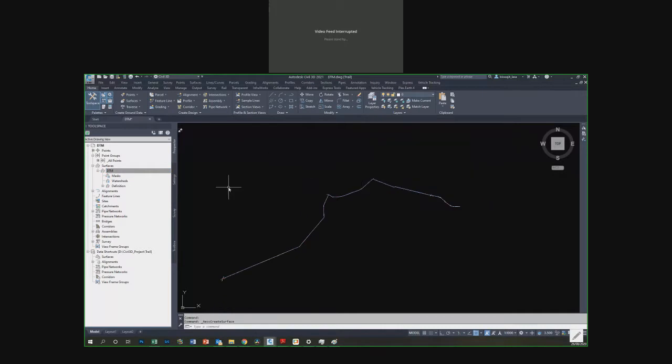So we need to insert the break lines as well as the point files, if you have contours or whatever things. You know the definition. This is the definition which defines this surface. You can have a boundary, a break line, a contour, a DEM file, that is digital elevation models, a drawing object, 3D drawing objects, or anything of that kind. So now you need to add a point file in it.